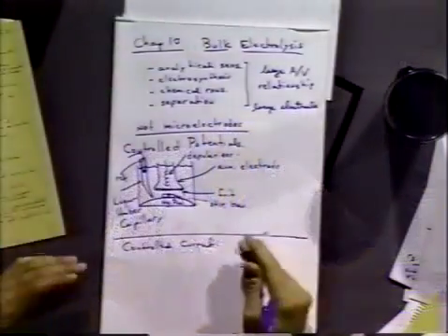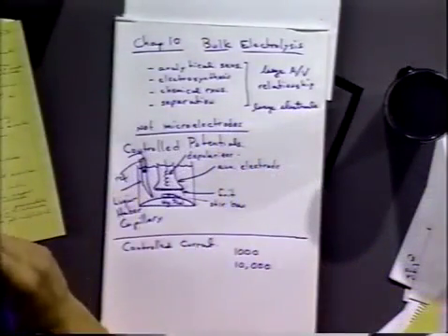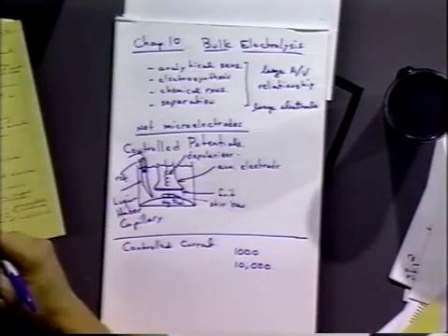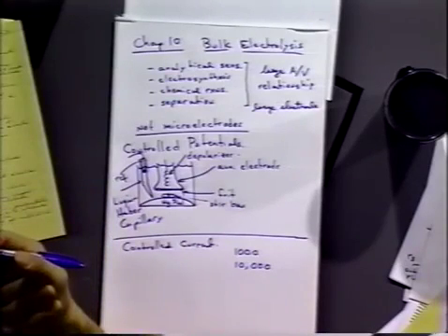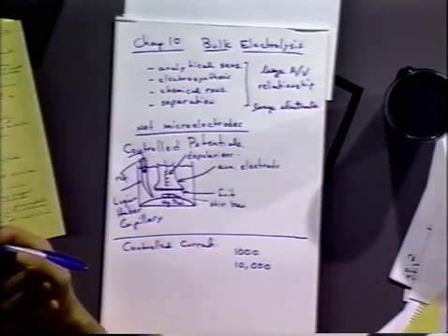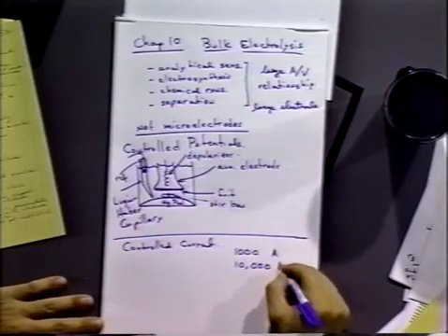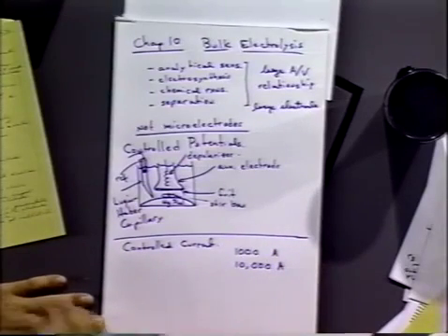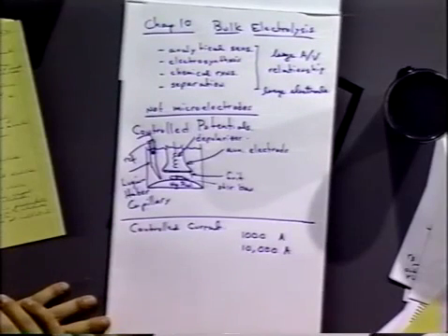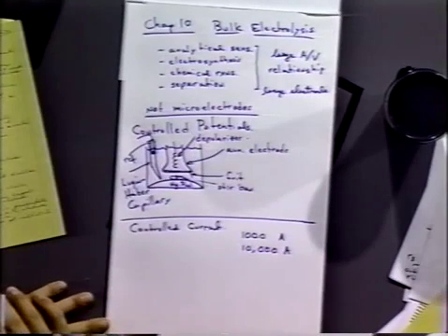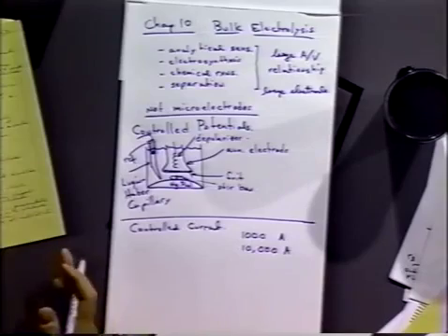But for big industrial processes, it's often a very efficient way to do this because, for example, it's very difficult to make a potentiostat that may be required to supply, say, 1,000 or 10,000 amps that you might be using in a cell for an aluminum electrolysis process or some other process. So you want to use a constant current mode. It's easier to supply these sorts of high currents. Not easy, but easier. And as I said, you have to make sure that you're not shifting the current.